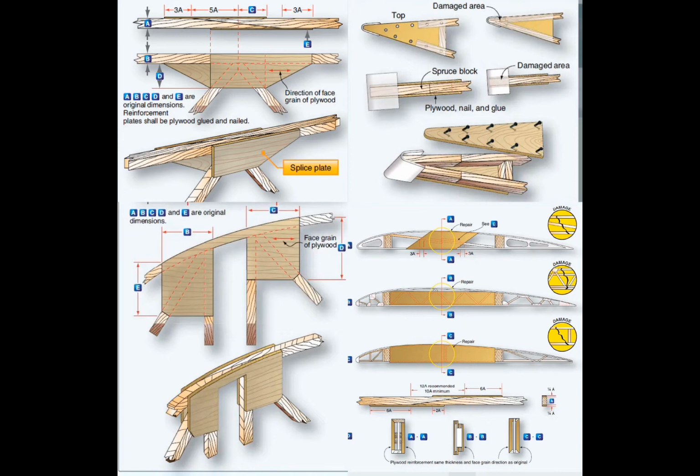What is the recommended clamping pressure for a glued joint? 125 to 150 psi. How long should a wood glue joint be kept under pressure before removing the clamps? Pressure time will vary depending on the temperature. It is recommended that it remain under pressure at about 85° Fahrenheit for a period of at least 7 hours.